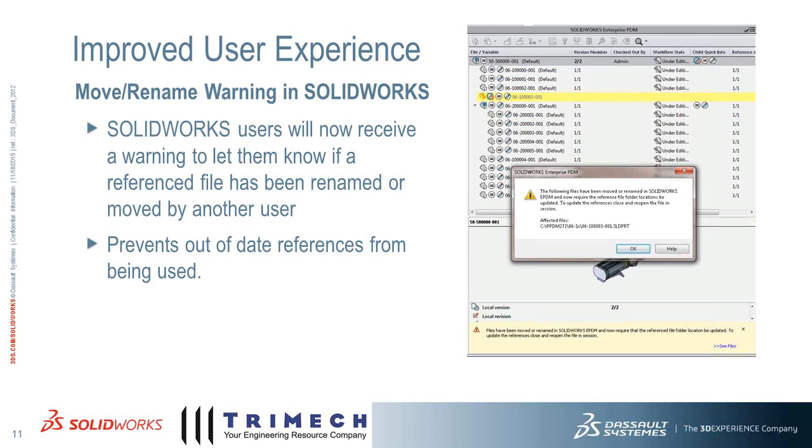To update the references, close and reopen the file in the session, and it gives a list of the affected files. So this is going to help prevent out-of-date references from being used for files that are being managed and modified inside of SolidWorks.